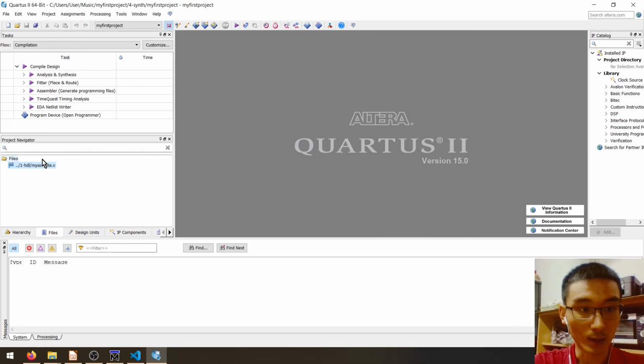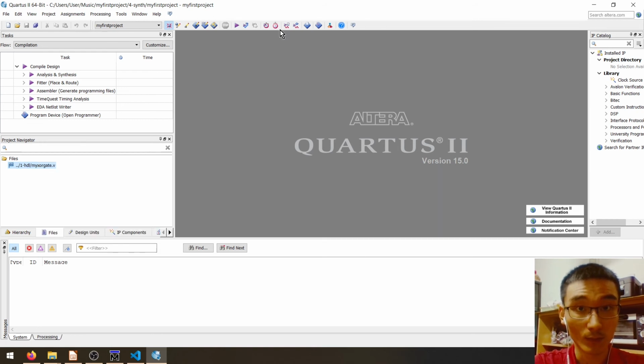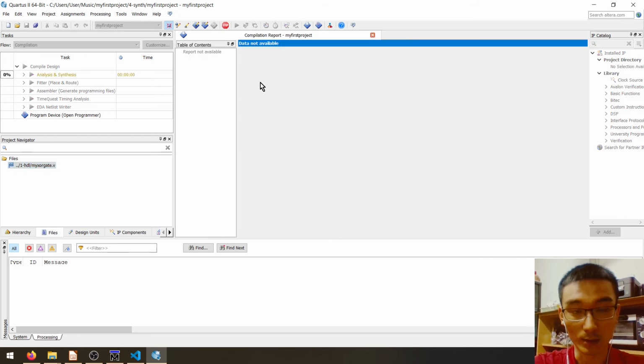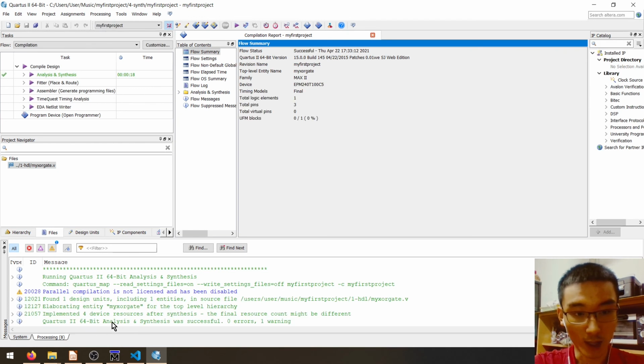To start analysis and synthesis, we can double click on this, or we can click on this button. But before that, make sure you right click and then set this as the top level entity. Only then you can start the analysis and synthesis. Alright, the analysis and synthesis was successful.